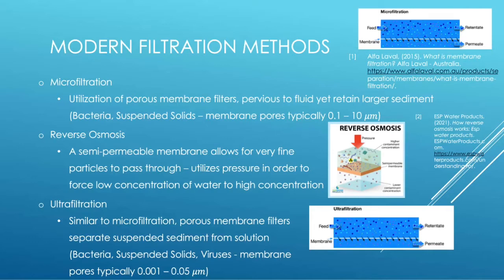Porous membrane filters separate the suspended sediment from solution. This could again be bacteria, suspended solids, or viruses, and the membrane pores are typically 0.001 to 0.05 micrometers. You can see an image of ultrafiltration right under the reverse osmosis image.